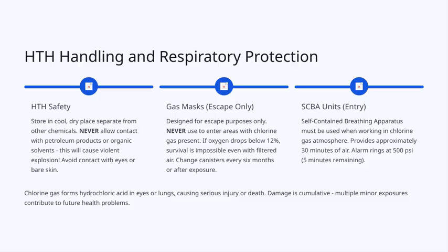Now, for emergency situations, we have gas masks designed specifically for escape purposes only. It's very important to understand that these masks are not meant for entering areas where chlorine gas is present. If oxygen levels drop below 12%, survival becomes impossible even with filtered air, so safety is paramount. Also, change the canisters every 6 months or after any exposure to ensure they remain effective.